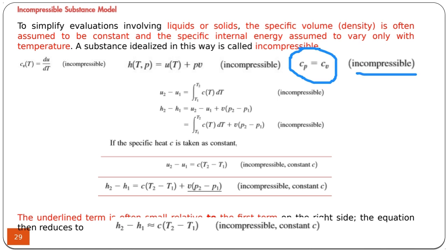The specific heats can vary with temperature. So in order to find the internal energy change during the temperature change, we may have to use an integral relationship, because Cv or Cp can be a function of temperature. In this case, we have to know the functional dependence of the specific heat on temperature so that we can perform this integral.